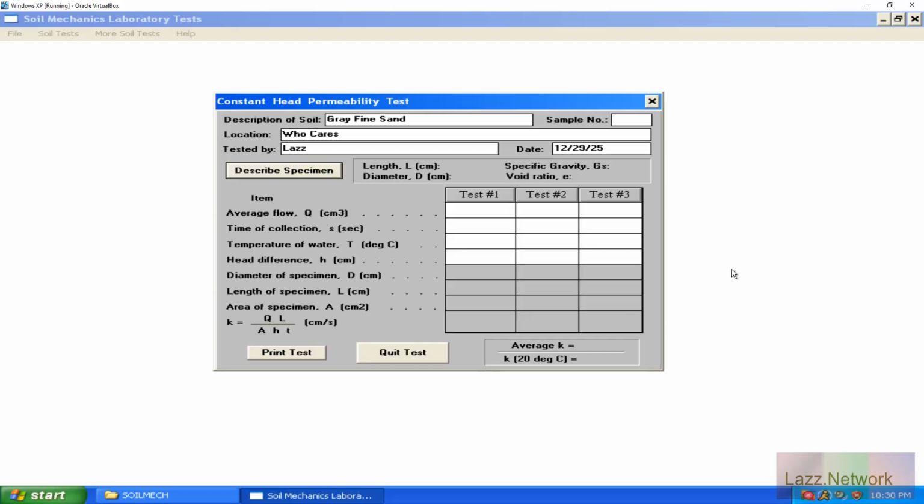Typically, if there's no compaction requirement, usually you'll air dry your soil. Like what I stated before, that's in an oven no greater than 140 degrees Fahrenheit or 60 degrees Celsius, or in front of a fan or something, until the catchphrase term, until it's friable under a trowel. So in other words, if you were to put a trowel or metal or anything in there, no sand particles are sticking to whatever you put in the sample itself.